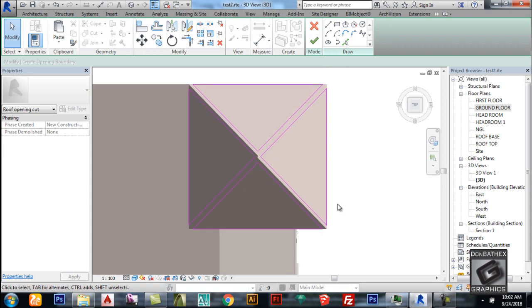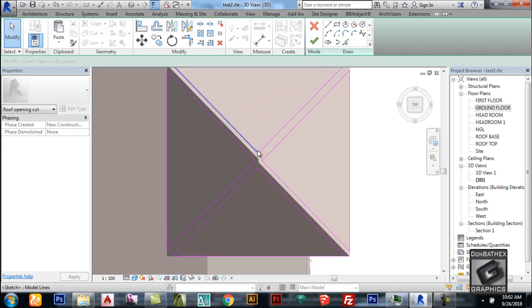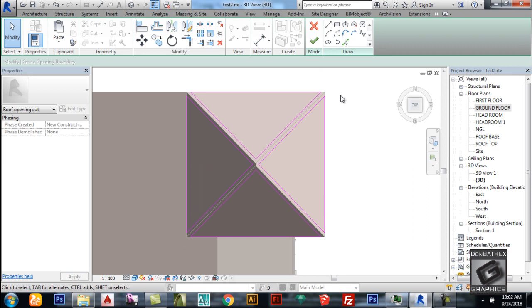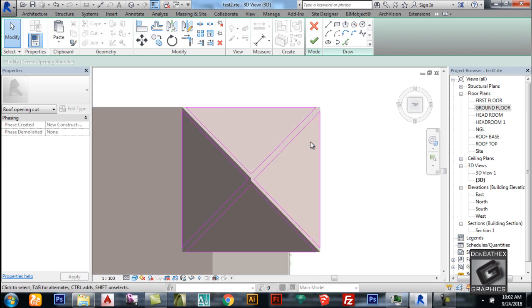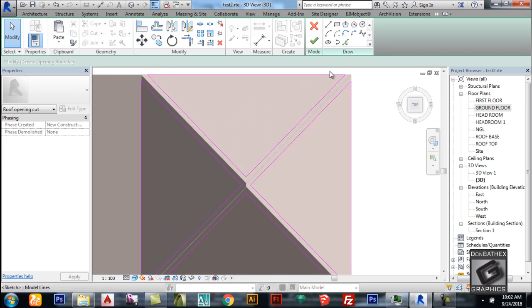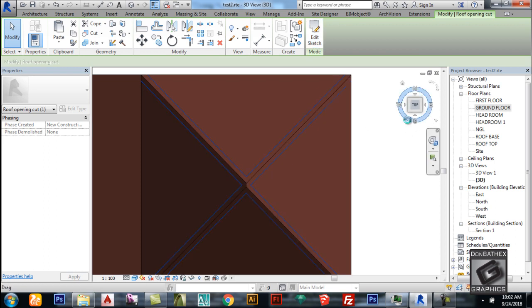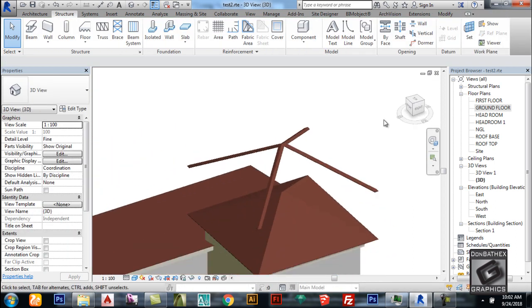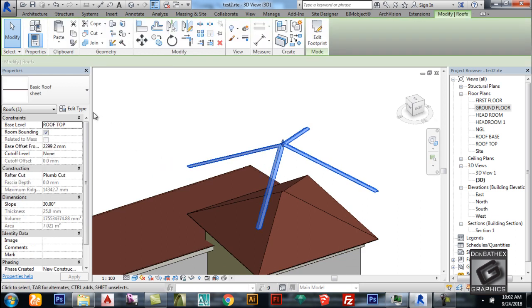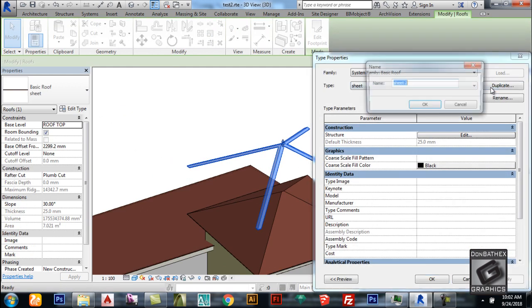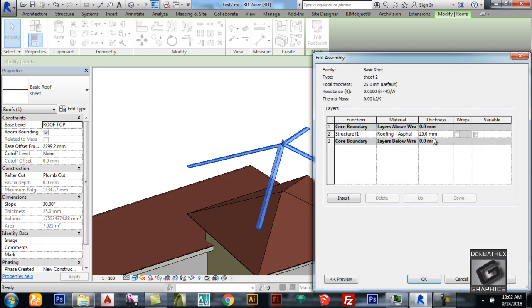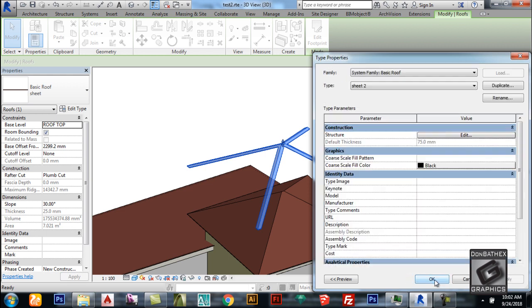I have a tutorial I made on this alone, so you can check my other videos. So if we finish this now, I will simply check it. You can see what we have. So edit type and duplicate it, and simply increase the thickness. Let's say 75.